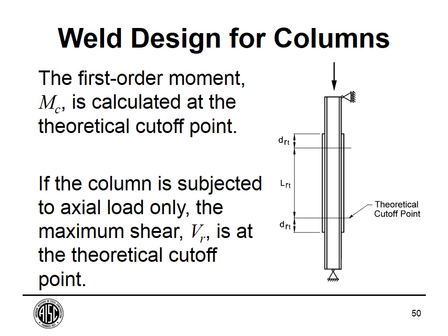You look at the load and say, well, I need a W14x90 for that load and that length of column. Well, it's kind of a similar thing. You just select a theoretical cutoff point that you think is economical and that will be good for your load. And if it's not right, you just have to iterate to find it, which is what I had to do in the composite beam example, do a couple of iterations on that.